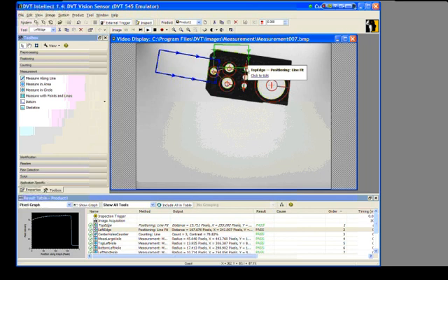I am also verifying that there are 3 holes here, so I'm counting the holes or these features, and then I am finding center points of these through holes and finding the angle between the lines connecting the centers of those circles or holes.